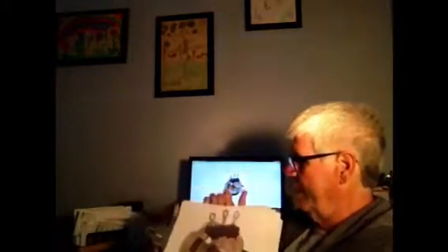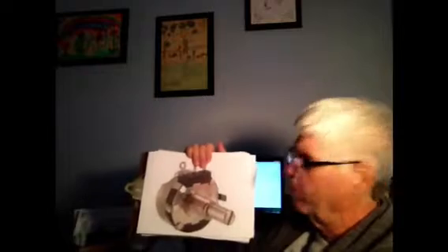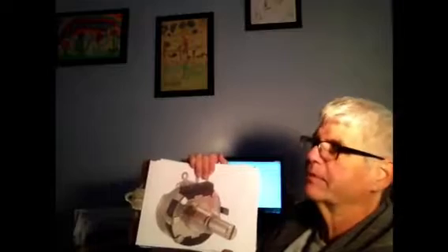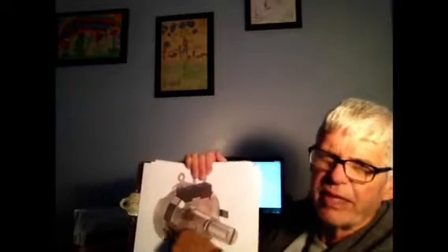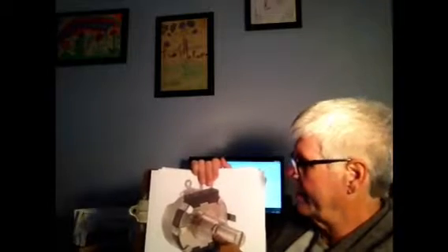Now then, potentiometers can develop problems, okay? That wiper that's sliding around inside over that resistor that's inside this little can get dirt under it. Good idea to get rid of that dirt. How can you? Well, there's two ways. One way, and probably the easiest way, is to get some electrical contact cleaner and spray it right there. It'll find its way inside there. That's not the best way, but it is the easiest way.